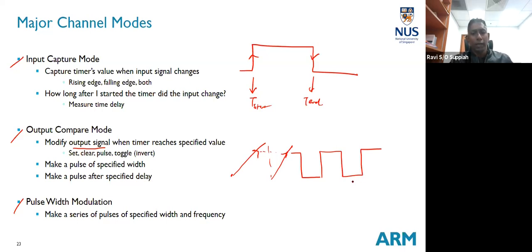Correct. If I just go back to what we did earlier, the programmable interrupt timer (PIT), I can also use this. Correct. I can just set the programmable interrupt timer to count for this particular duration, and every time the interrupt is triggered, I go and toggle the GPIO. Correct. Okay. So why do we still want to use this?